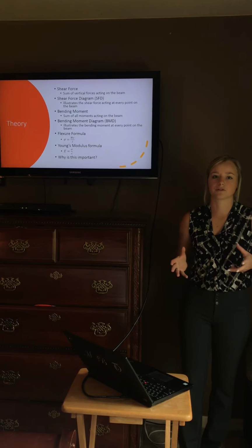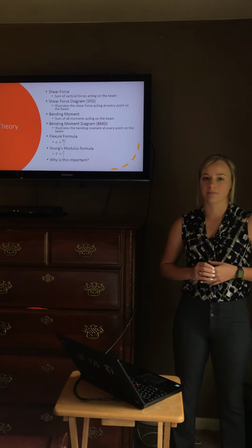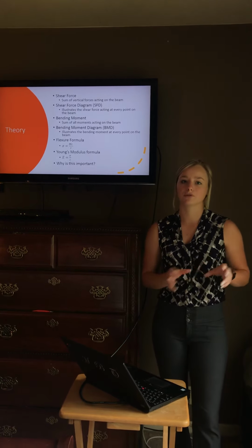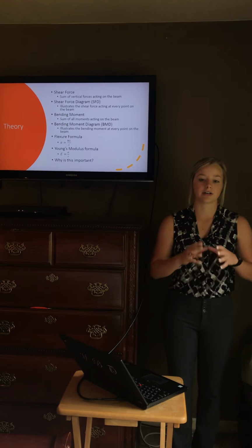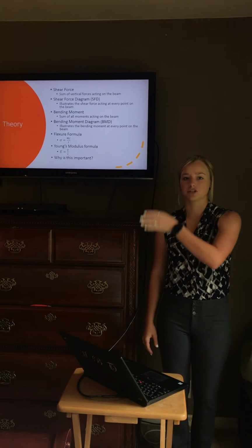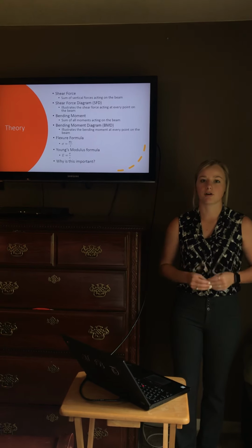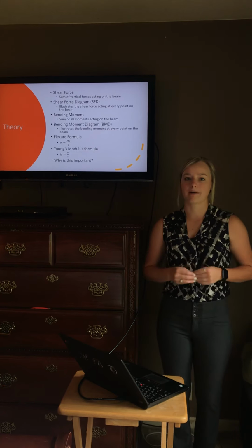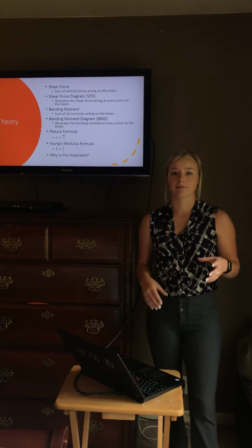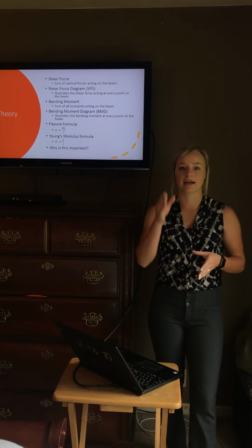So what is shear force? Shear force is the sum of all the vertical forces acting along a beam. So the shear force diagram is an illustration of those forces, and it illustrates the entire length of the beam, so you could go to any point along the beam and find the shear force acting on that point. Bending moment is the sum of all of the bending moments acting on that beam. Just like the shear force diagram, the bending moment diagram is an illustration of the entire beam, and you can find the bending moment at each point.